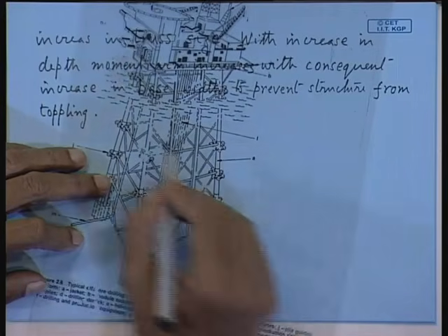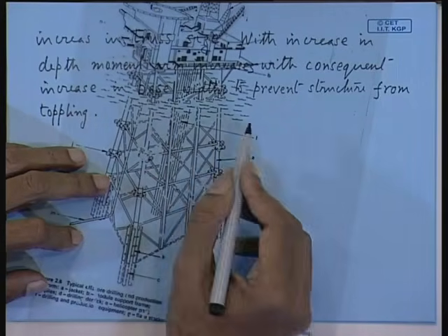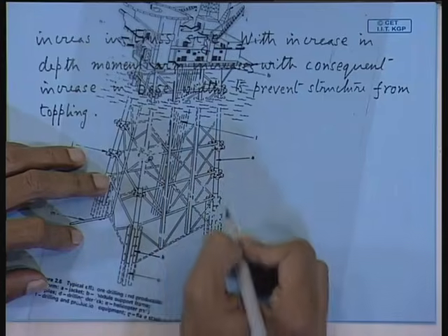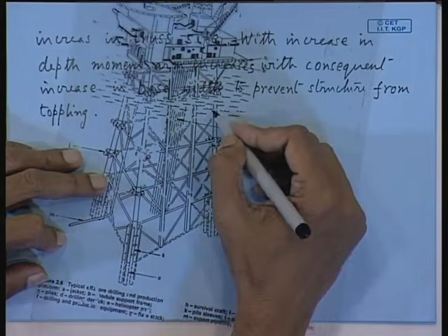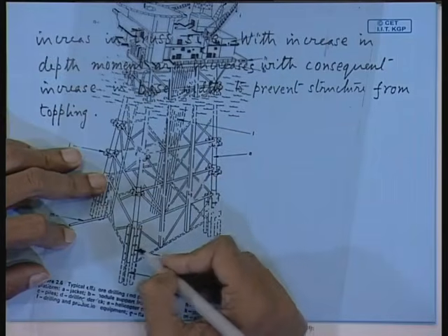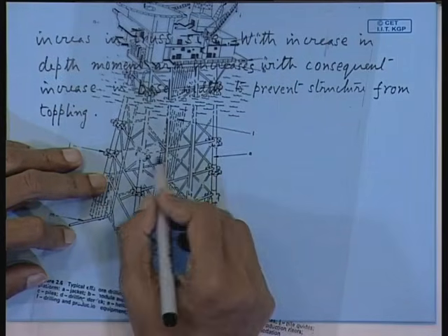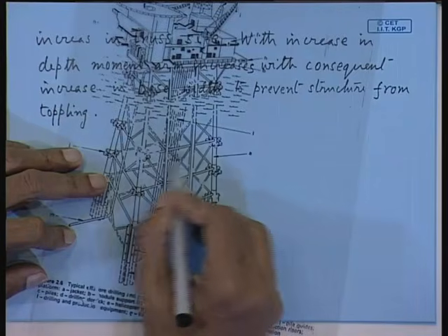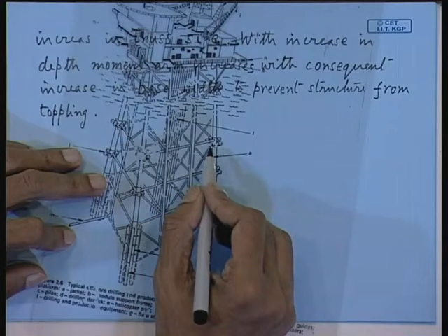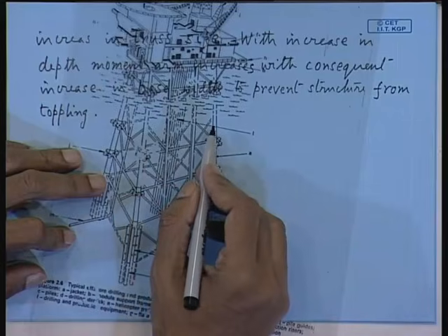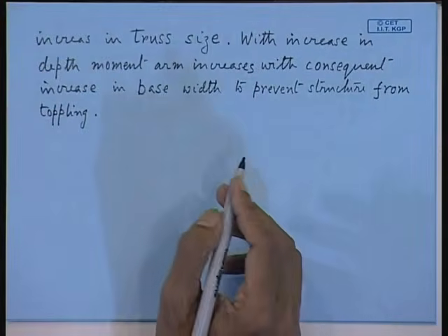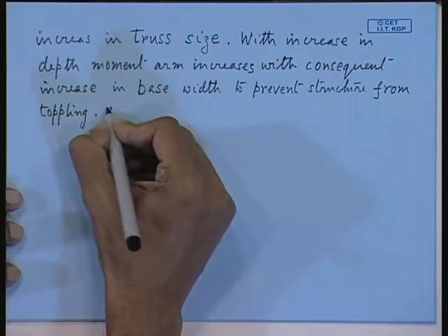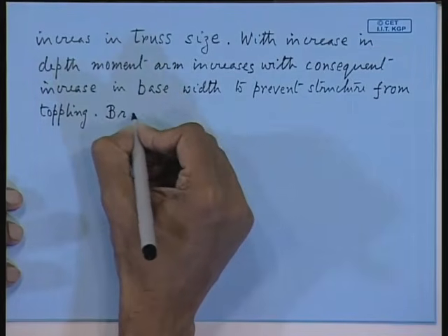Followed. Now, the structure has also increased in size, both depth wise and breadth wise. So, now you cannot have the same thickness of bracing members, because a greater amount of load is going to come. So, bracing member thicknesses will also be increased.